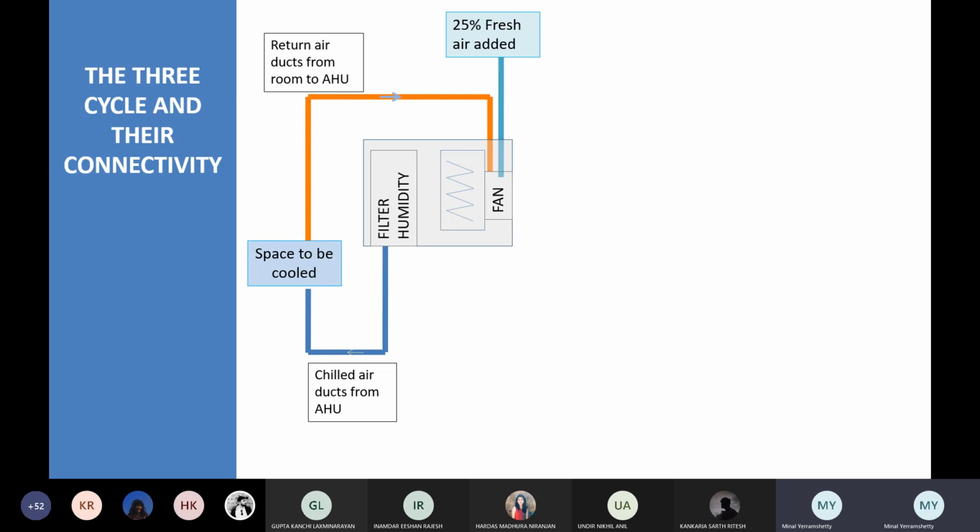So that is how, the dirty air, or I would say warm air, or maybe mingled with somebody smoking there, all those particles will come here, okay. Also along with it, this air will come in. Both pass through the chilled air and finally it gets filtered and goes ahead. Now in many diagrams you will see that the filter is placed first, that also works. Basically it all happens in a duct. So from the fan it goes to the filter, from the filter to the coil, from the coil to humidity control, and then it goes out into the room.